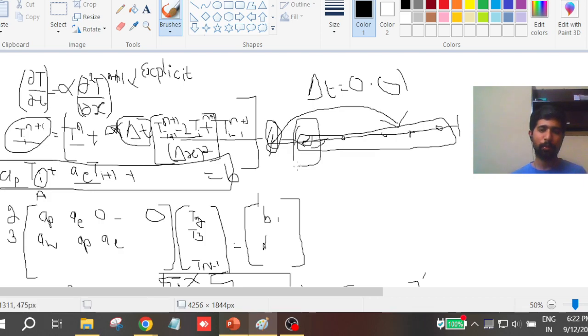Now you try to calculate using the old values of the neighboring grid points, whose values will not be physical. Because in actual reality the wave is not there in this domain completely, it has gone out. That happens with a pulse. So it becomes very unphysical to take very high delta t in an explicit time marching.